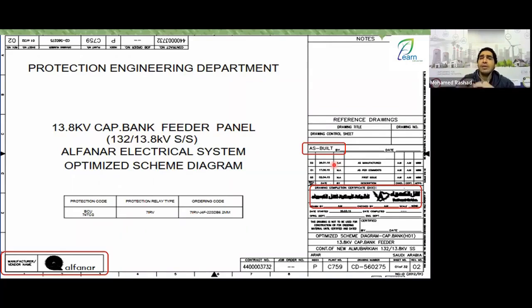Once the station is operational, you take your drawing and give it to the designer. The designer then incorporates the final modifications as the station is now energized and operating with these changes. They draw it up and send you the as-built drawing, which reflects how it is currently built and how the station is operating. This is the final version you have at your station. All right, great. This is what we refer to as the as-built.